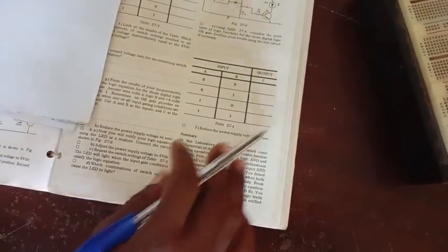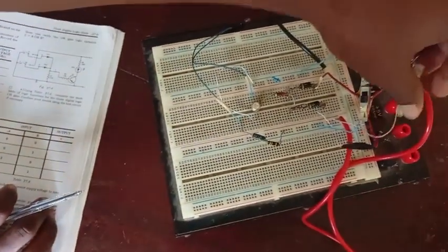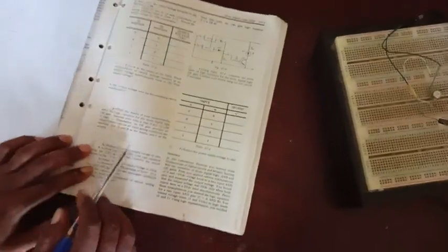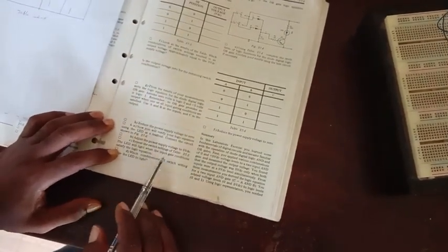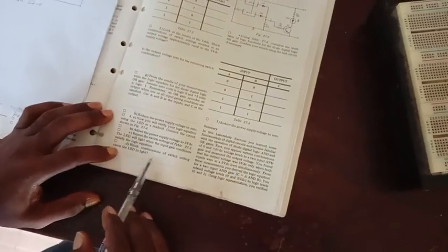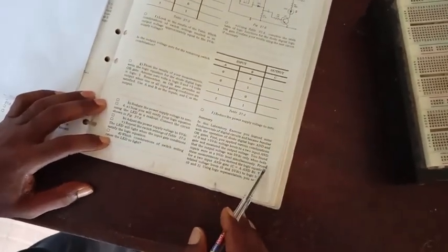So this is what we are asked to do at table 27 to 4. So this verifies the OR gate. So reduce the power supply to 0. So let's reduce it back to 0. So we have 0, everything. Our lamp is off. So let's see what we are asked to do. Adjust power supply to 5 volts. We've done that. Repeat the switching. We have done that. Which combination of the switching setting?